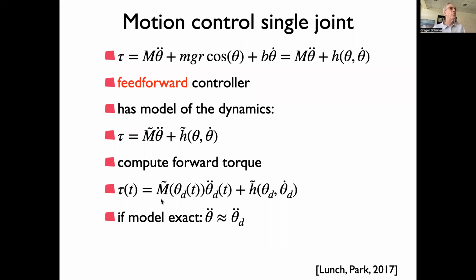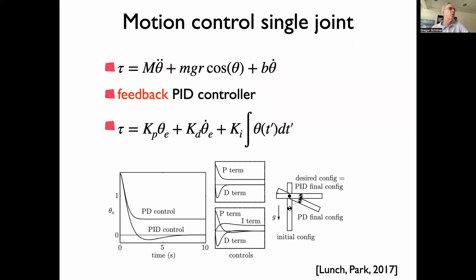how you can now make more intelligent kind of controllers, where you take into account from the head that you can predict the kind of things that will happen, right? So again, when here I said feedback in the sense that this torque that you apply takes into account stuff that you have observed, error, rate of change of error, integral of error, and then you control. Yeah? So there's feeding back information that you've already observed.